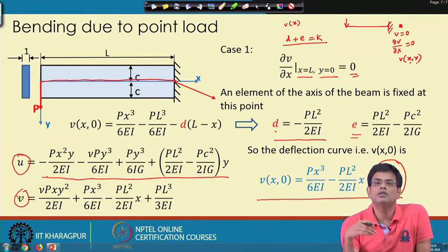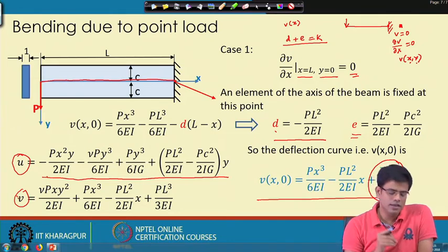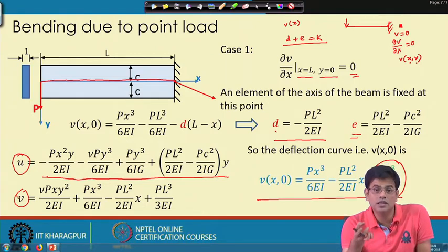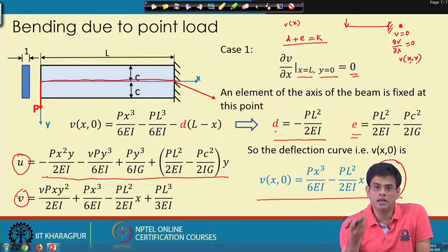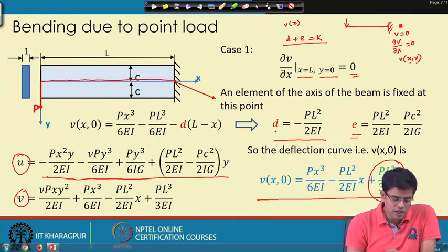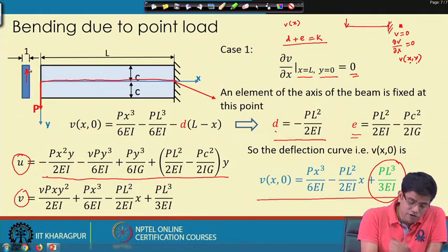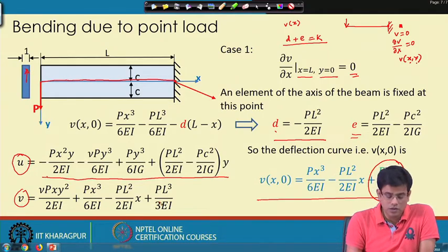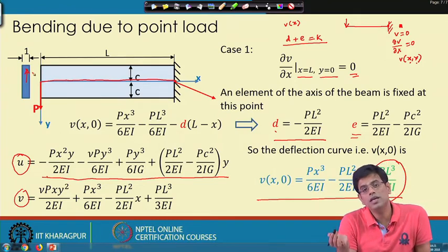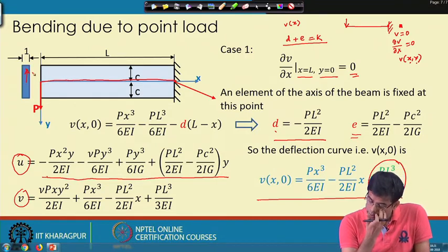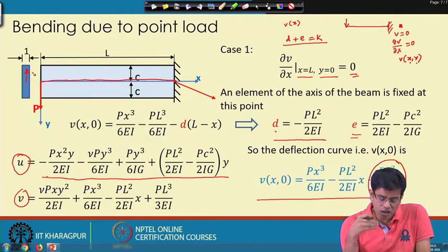So, through this stress function approach, what we have achieved is a more accurate expression if the beam is two dimensional. If we consider the beam as two dimensional, we now know the displacements in the x direction and in the y direction. For instance, if I want the displacement of the cross section at a distance y from something, this expression will directly give me the cross sectional displacement of the beam. This can also be extended to the three-dimensional problem, but the expression will be very lengthy and complicated. The basic idea is to know the procedure and how we can approach this kind of problem.